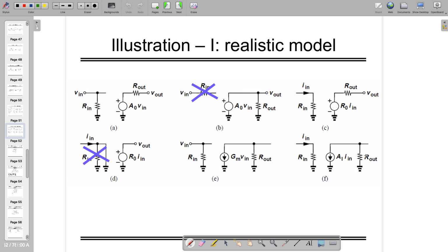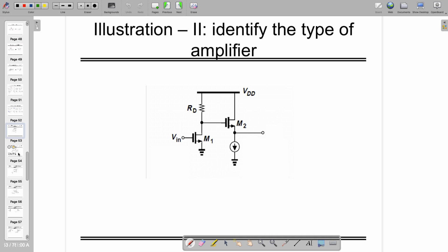So this is very important, and while keeping negative feedback, make sure that it's negative feedback only, because sometimes it happens that it's positive feedback. If it is positive, no matter what you are doing, the output will go either to 0 or VDD, and you end up with an unstable or oscillatory system. So for that, it has to be understood which kind of amplifier it is. Already we did such kind of things.